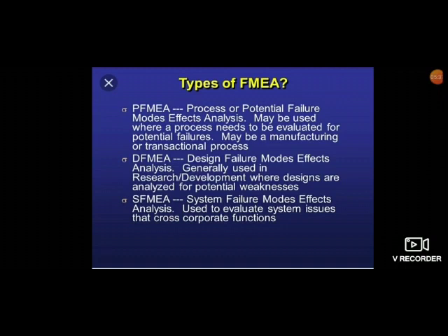Now, the second one, design failure mode and effect analysis, is a methodical approach used for identifying potential risks introduced in a new or changed design of a product or service. It initially identifies design functions, failure modes and their effects on the customers, with a corresponding severity ranking or danger of the effect.